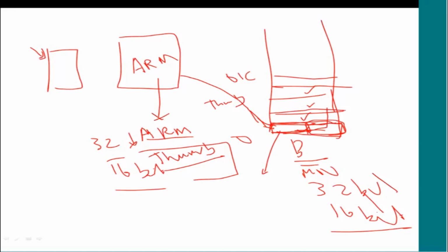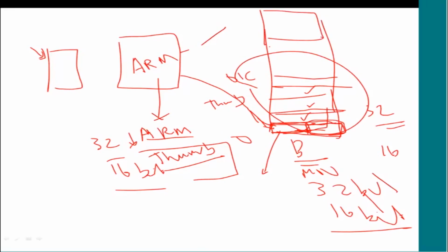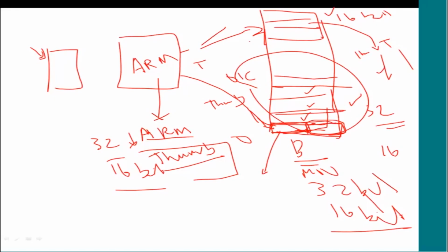What you store here, you can decide to put either a 32-bit instruction or a 16-bit instruction. You can't have both. If you want to have both, whenever the mode changes you have to come and reload it with something else, which will be time consuming and not suitable for a real-time system. Another option is to reserve one more table, a 16-bit mode table. So the processor will think, I am in Thumb mode, so let me go to this vector table and access it. Then this handler also should be in Thumb mode. So effectively you will be managing two things, both handler as well as vector table, with lots of confusion, and it is actually impacting the performance of the system.